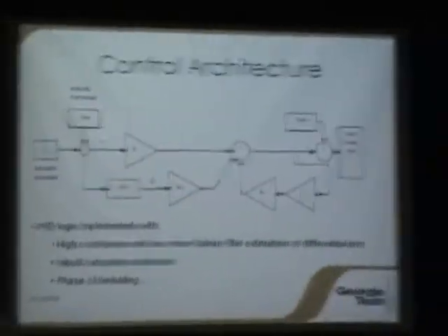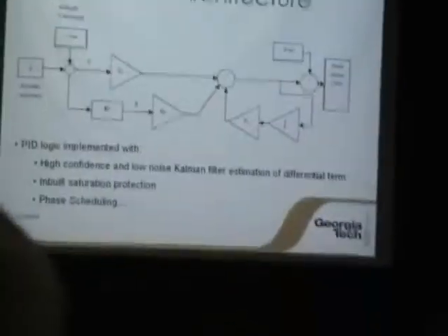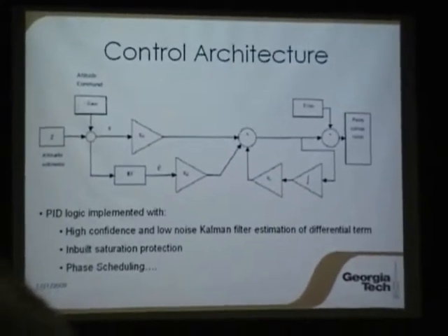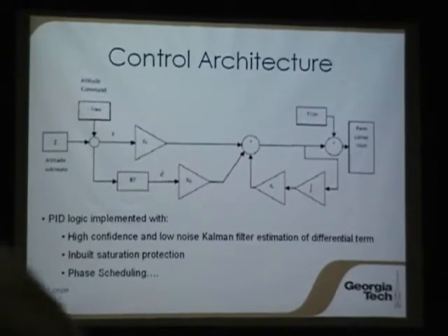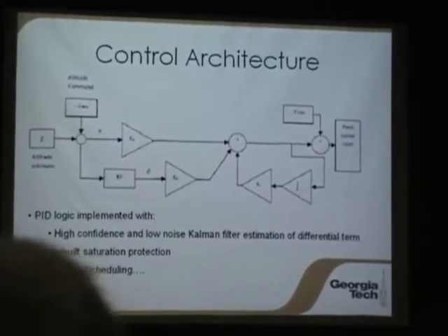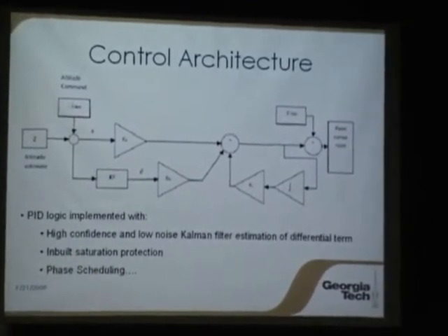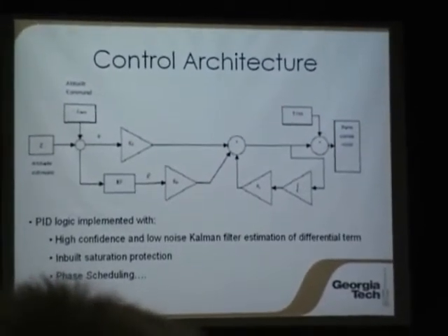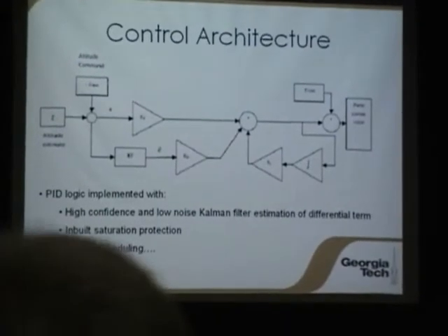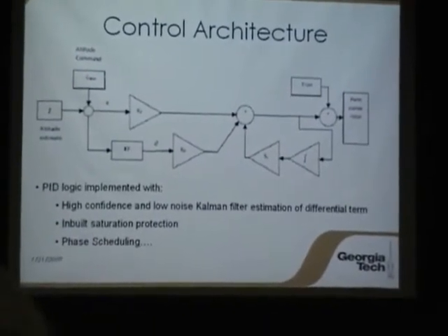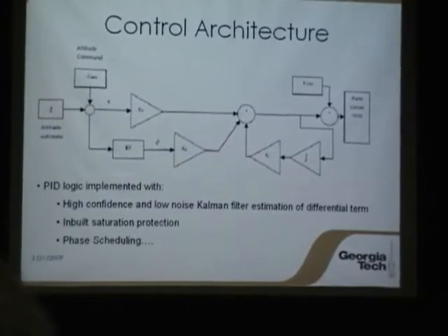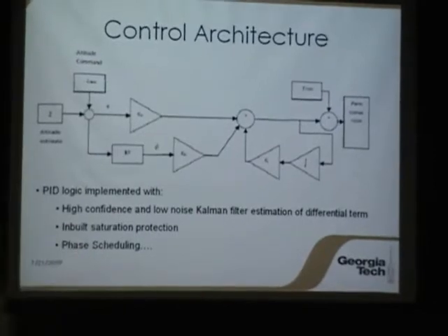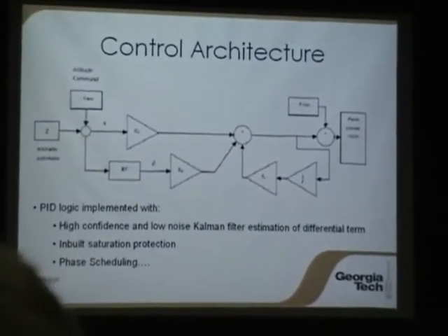It's not a good idea to numerically differentiate these range measurements to get the velocity, because you're going to end up with really high noise and weird numbers if you somehow get an outlier. When you're facing an obstacle, you don't really know whether the obstacle is moving or whether it's stationary. You don't know the topography of the obstacle. You don't know anything. So you have to be really careful with what you do with those measurements. So we proposed using a Kalman filter based estimation of relative velocity, that's what we call the relative velocity to an obstacle.